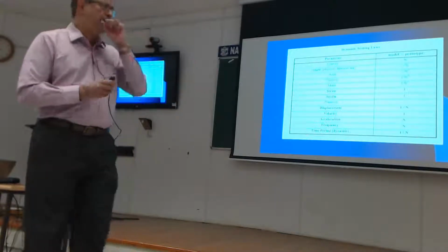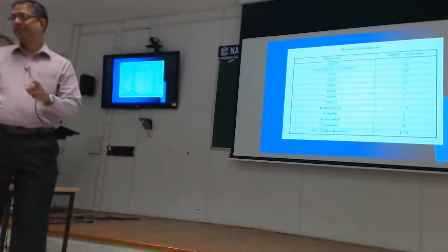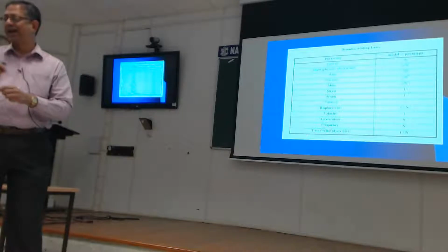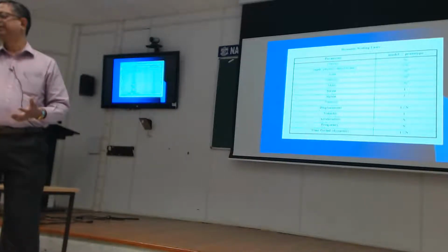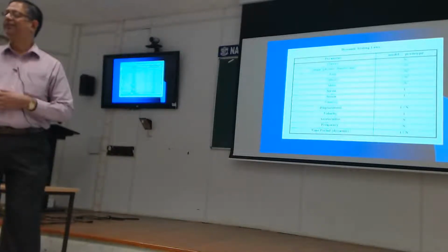So if my entire earthquake lasts only half a second, I need to be logging each channel or each instrument at maybe 5 or 6 kilohertz. And if there are 60 of them, I need a throughput of 360 kilohertz.